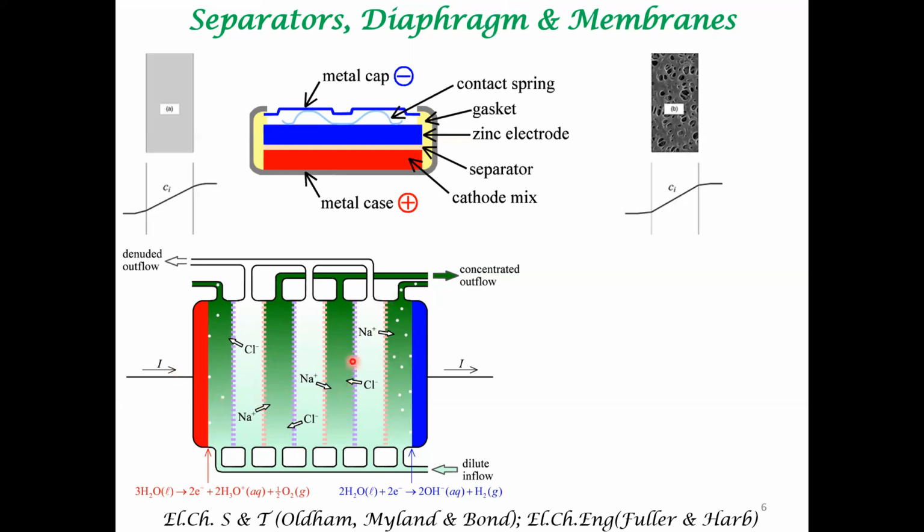But of late, how to generate and stabilize these kinds of membranes, a lot more research is being done of late. But what I want to emphasize here is the nature of these membranes. These membranes are used for selectively transporting ions. The most popular membrane is called the Nafion membrane, which is a proton selective or cation selective membrane, often used in fuel cells and water electrolyzers.